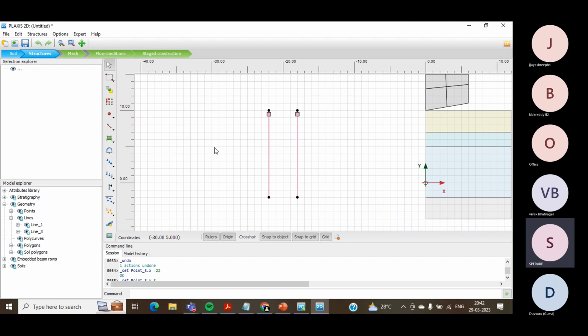But make sure that the moment you are moving from structures to mesh, always hint to the software that you also need to check the geometry. That's why you click on this Check Geometry. Check Geometry will collect the inputs and give them to the mesh in the backend. When the mesh is started, if any merged components are there, then automatically it will try to delete those particular components.